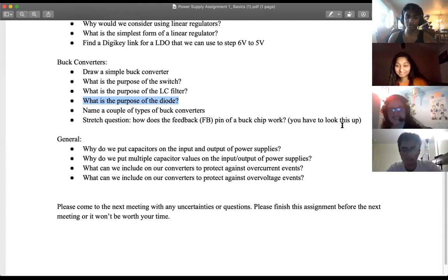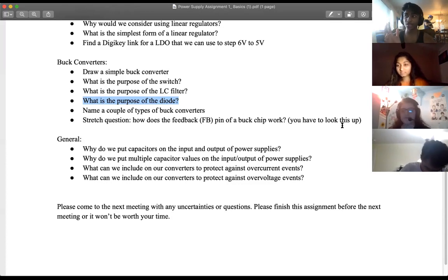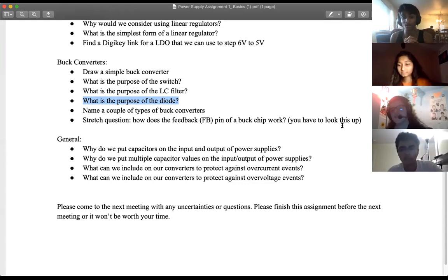So your inductor is building up energy in the form of a magnetic field. We'll talk about capacitors in a bit today, but inductors and capacitors are kind of opposites, or inverses. They're both energy storage devices, but they behave differently, almost oppositely. Capacitors don't mind changing currents, but they hate changing voltages. Inductors don't mind changing voltages, but hate changing currents.